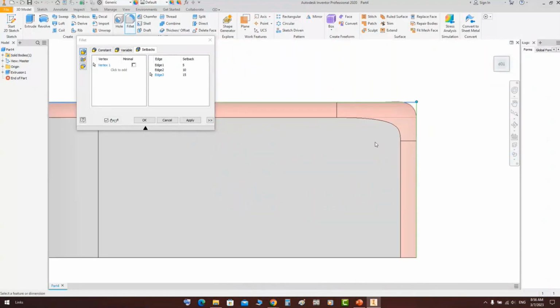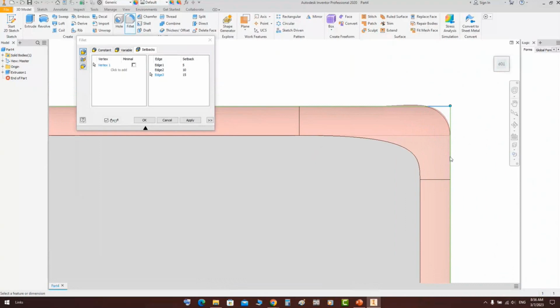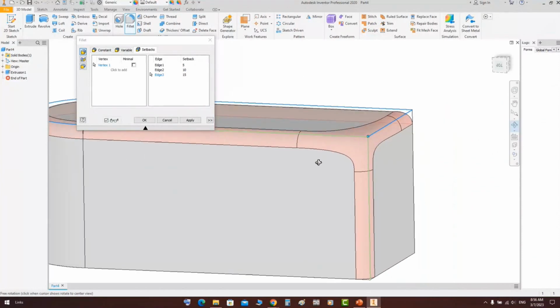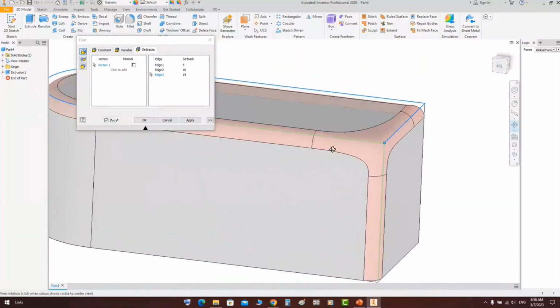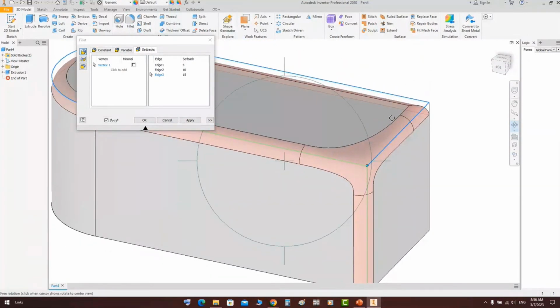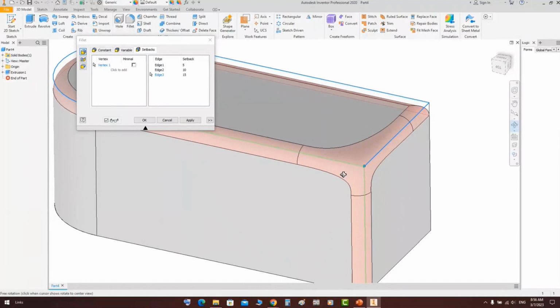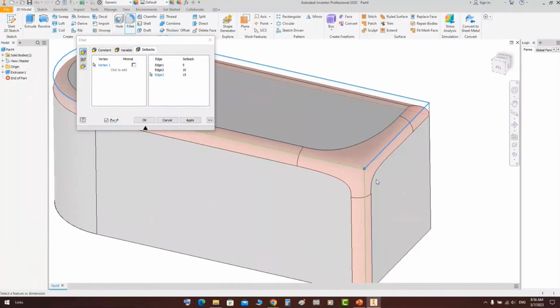If you take a look at that one, you will be able to make a fillet with 5 offset from the edge here and 10 on that edge. So by using this option, which is setback, you can modify the setback configuration of the intersect of the surfaces at the end point here.